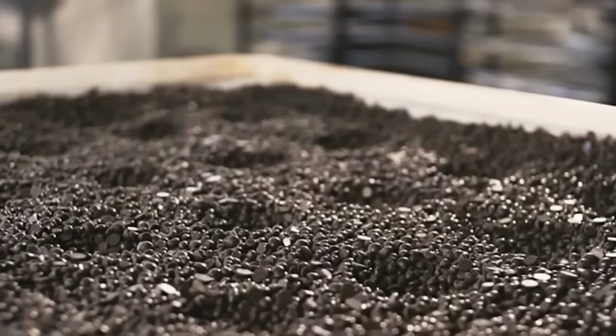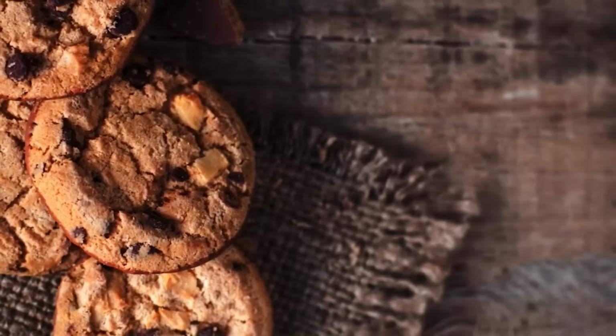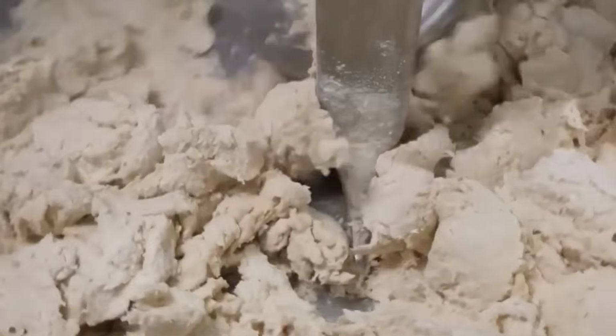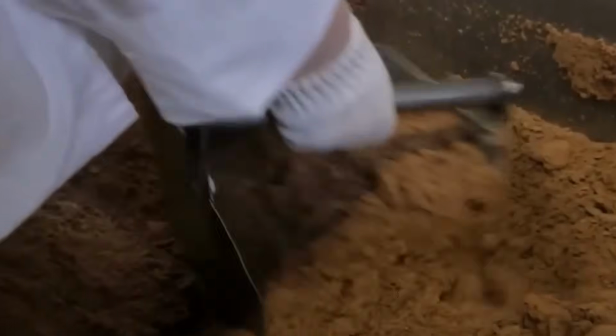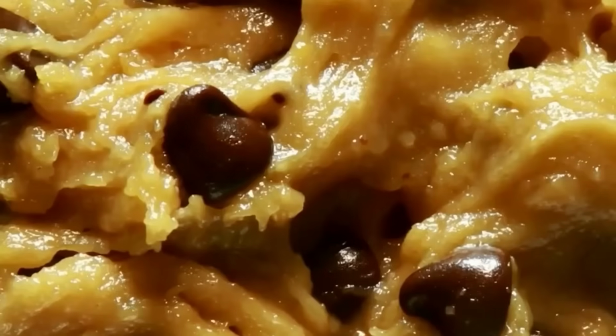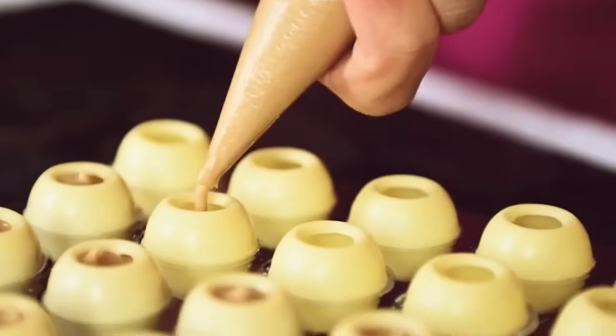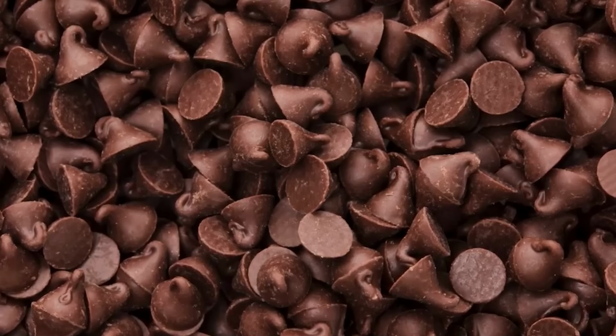Granulated sugar, brown sugar, cocoa solids, salt, and baking soda are stored in indoor silos or gravity-fed bins and fed into weigh stations using screw feeders with plus or minus 0.1% dosing precision. Vegetable shortening and liquid invert sugar are stored in stainless steel jacketed tanks with continuous recirculation to prevent phase separation. The shortening is heated to maintain fluidity at 45 to 50 degrees Celsius, and the invert sugar is pumped at a constant rate through positive displacement pumps.